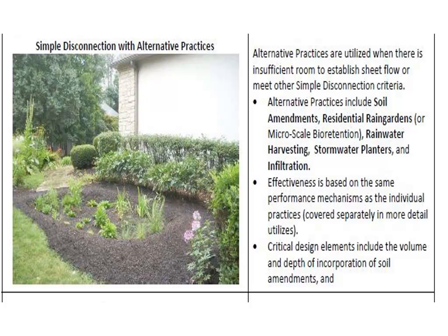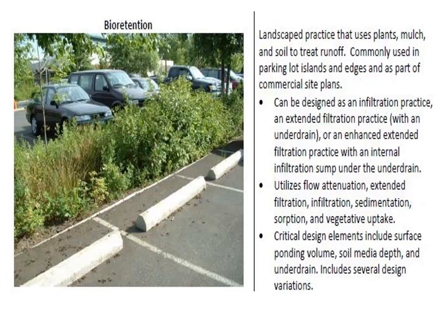It's just that some people don't like them because they require a little bit of maintenance. The soil pores can get clogged with silt, and so occasionally something like this may need to be refurbished. The soil could possibly have to be excavated and replaced. That's the hope, is to put in soils there that have sandy characteristics, or mix it with gravel, so that you don't have standing water for too long. Because you're right, mosquitoes would be very unpleasant.